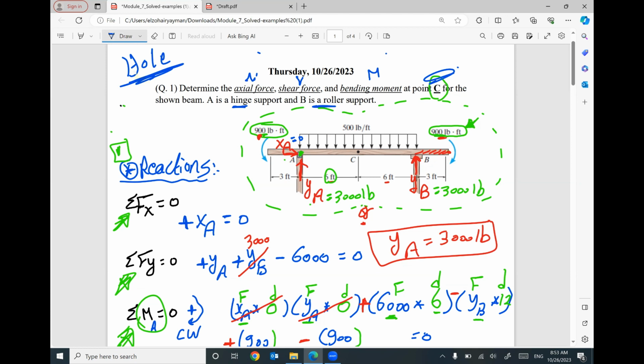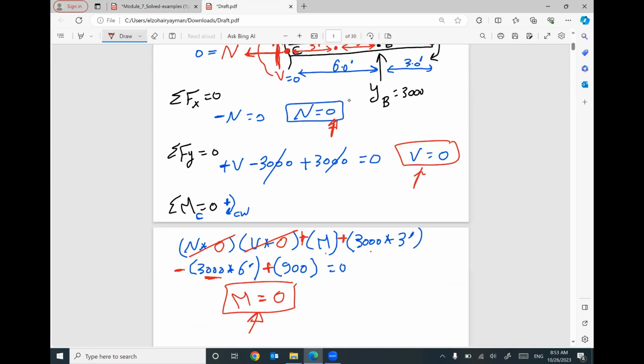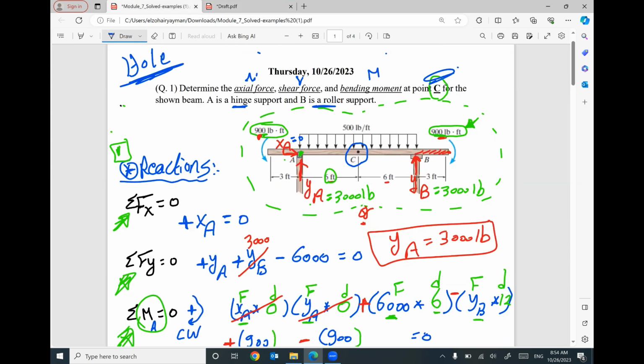But I think point C will be the best point to make or to drill a hole. Do you know why? Because at point C, we don't have any internal forces. Nothing, no stress. This point is not stressed at all in this beam. Just, I would like to give you just a hint. What is the main benefit of engineering mechanics?